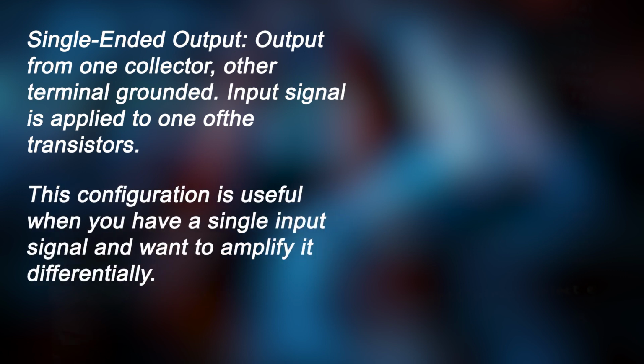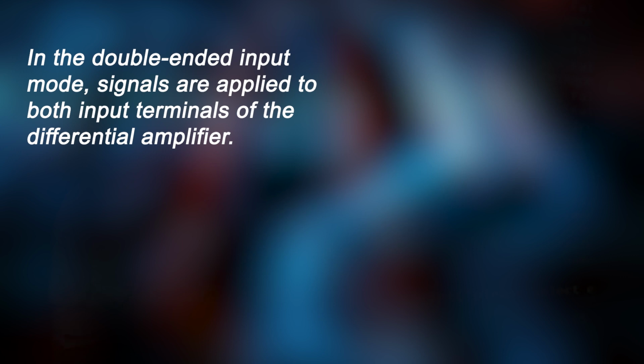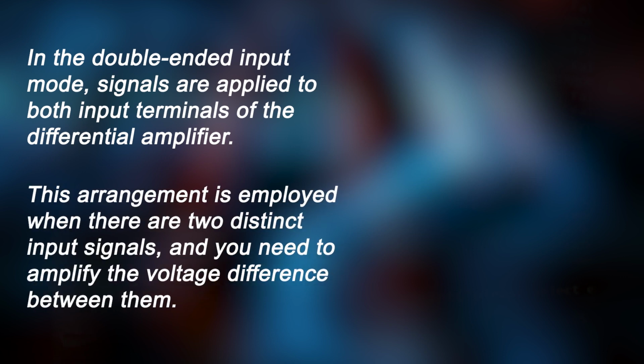This setup is chosen when you require a single-ended output, often used in applications where only one polarity of the signal matters. Double-ended output. In the double-ended output mode, the output signal is taken from the voltage difference between two terminals, typically between the collectors of transistors T1 and T2.